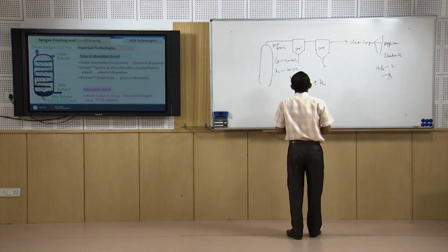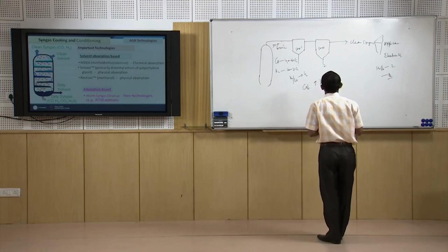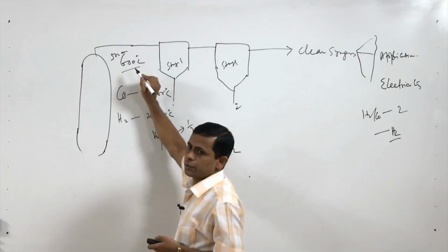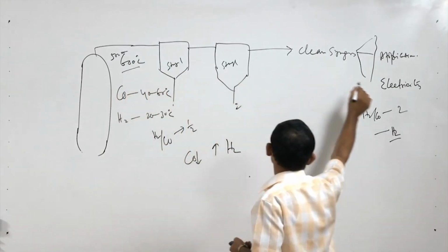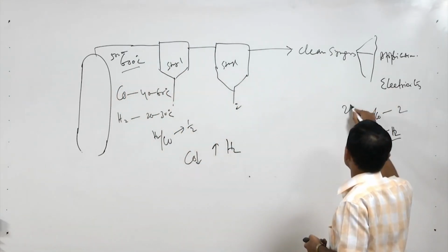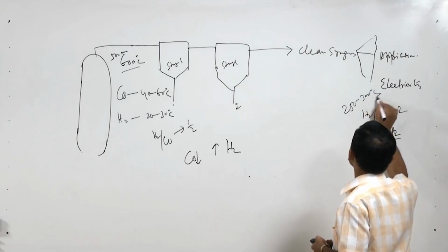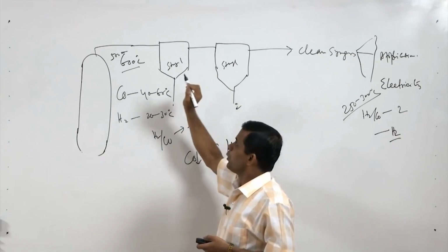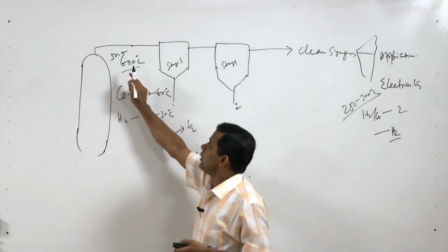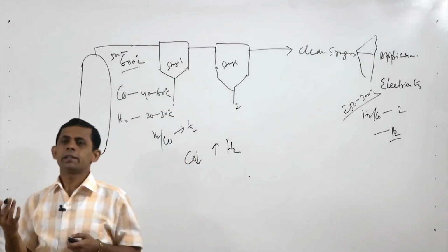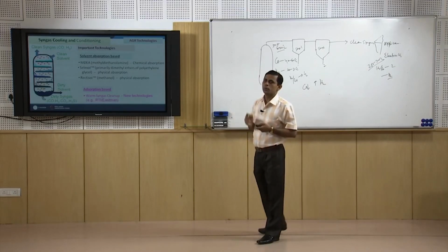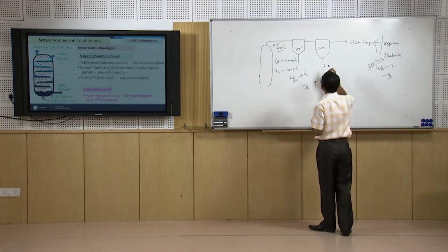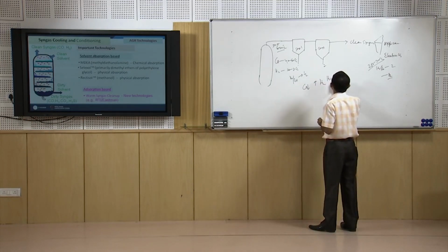Now, if we see on the flow sheet, it is clear to us that this is 500 to 600 degree centigrade. Again, in most of the cases 250 to 300 degree centigrade is required. So, if we can treat this hot gas at warm condition, then it will be more economically feasible. But in conventional cleaning stages for H2S and CO2 separation,